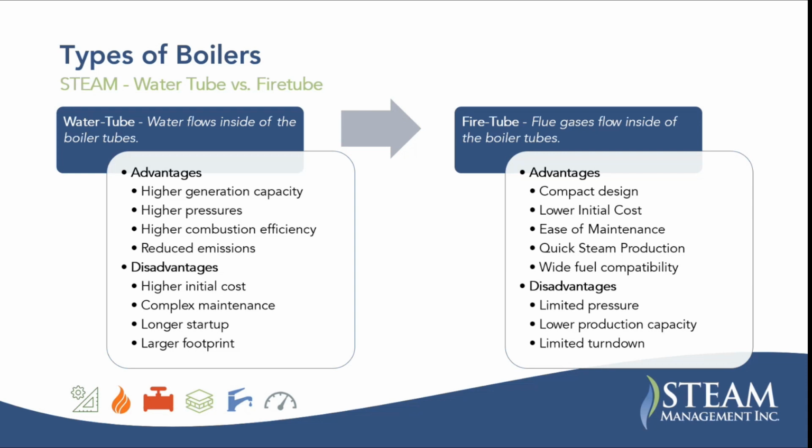If you think about the shape of it, in a water tube boiler all of your water and steam is contained inside of tubes and drums. And from a pressure standpoint, it's just stronger to have it in that type of vessel. Whereas in a fire tube boiler, you have a cylindrical vessel. It's just like a big tank, and it usually doesn't have domed ends or anything like that. It's just a cylinder full of water. And as you can imagine, that doesn't lend itself to being pressure resistant. So that's the most constraining factor between the two.